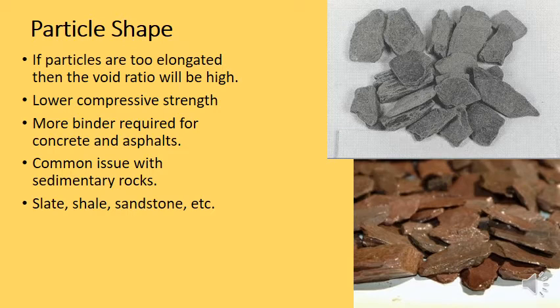And so when you break it with a rock crusher, it actually forms these flaky cornflakes, depending on the type of sedimentary rock. So sedimentary rocks like shale, sandstone, slate, if they have a low strength between the strata, these sort of layers or sheeting of minerals, then when you put it through a rock crusher, the aggregate particles will be flaky in this sort of shape.